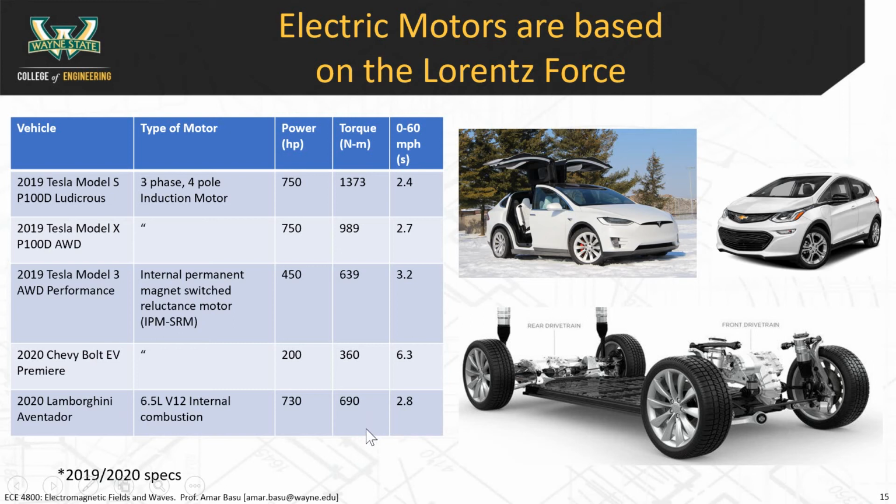Gasoline engines produce maximum torque when they're at high RPM, so when the engines are already going at a certain speed. So when these vehicles are going fast, they generate the maximum torque. Electric motors, on the other hand, generate their maximum torque when they're standing still. That's right, when there's 0 RPM and 0 motion on the wheel. One of the interesting things about that is that electric motors are designed with certain specifications. They can have much greater levels of torque than gasoline engines can.